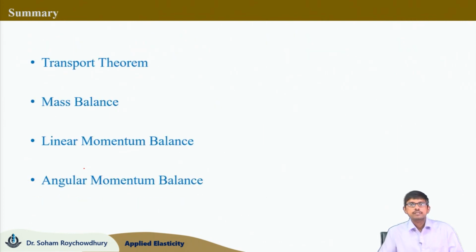So, in this lecture we first introduced the transport theorem, and with the help of that, in the deformed coordinate we derived the expression of mass balance, then linear momentum balance, which basically results in the static equilibrium equation for the static problem, and then finally angular momentum balance, resulting in the equality of the cross shear components of the Cauchy stress.